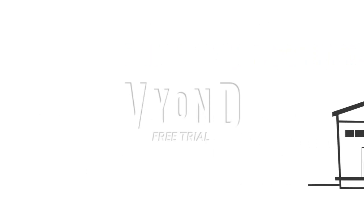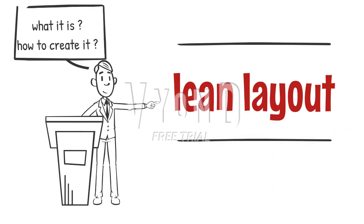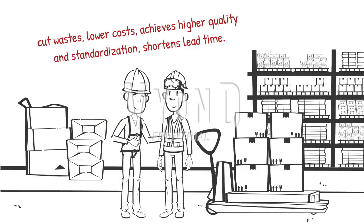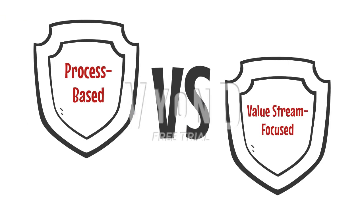A lean plant layout applies lean manufacturing principles to cut wastes, lower costs, achieve higher quality and standardization, and shorten lead time. Lean facilities create a seamless flow for information and minimize handling time and effort. So what's the difference between traditional and lean plant layouts? Traditional plant layout focuses more on process-based departments. Similar machines are grouped into functional work centers or workshops. A typical traditional machinery factory might be separated into workshops of cutting, fabrication, machining, and assembly.